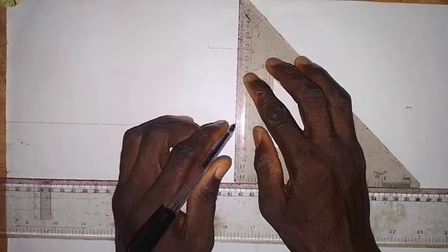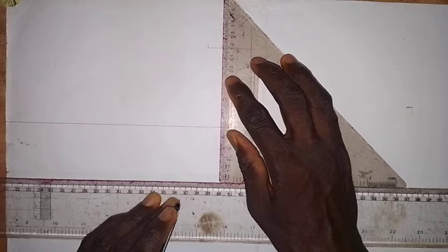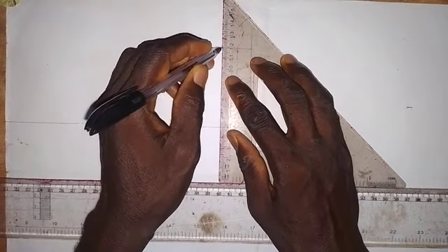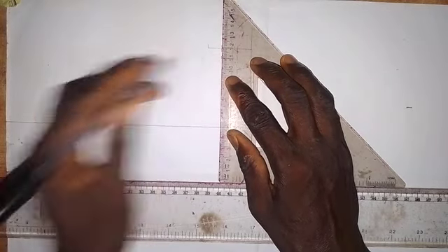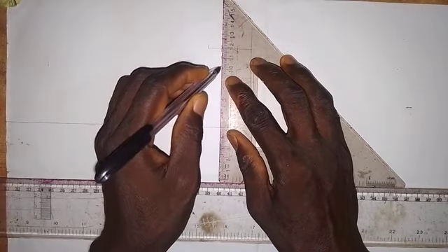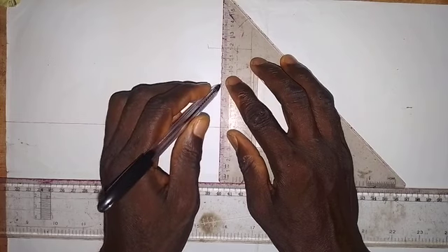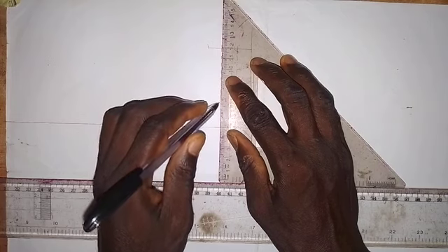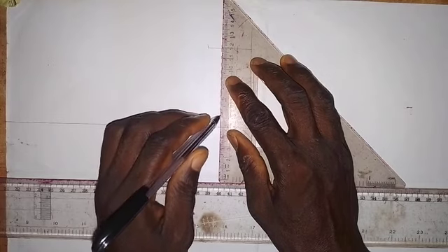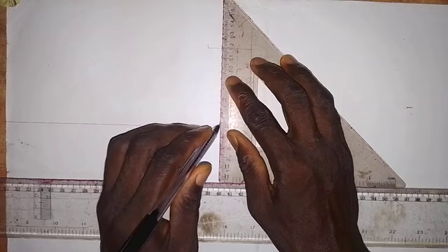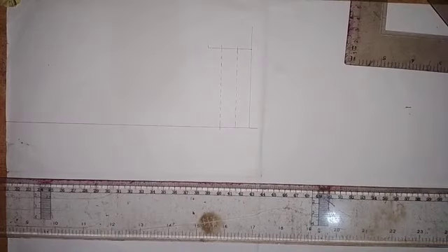Because that cut part is hidden from us in the front elevation, we also have the same thing here. So we draw it with short dashes line, as I'm doing it here, because it is hidden from us. We can't see it in the front elevation on that surface. Alright, so we have the short dashes line, so we have produced that.